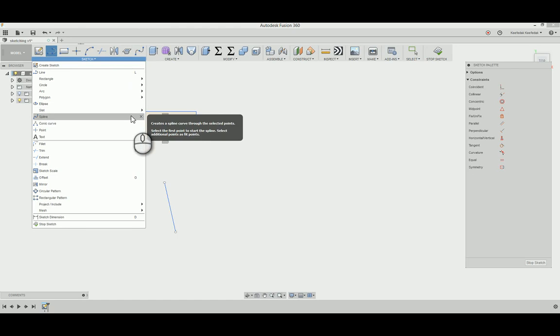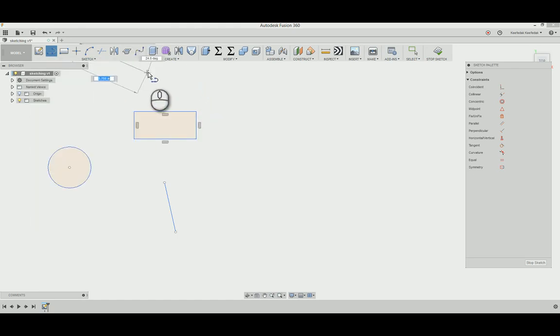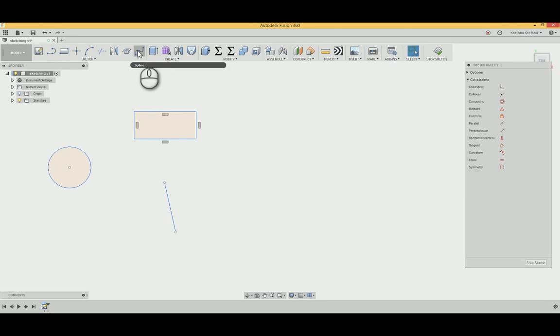So we're going to click the spline. I pinned it. And splines are really cool. I love them. Very curvy. And with that, you're going to just click, click, click, just like a bunch of them, and then join them up together. Once you've got it joined together, hit escape.